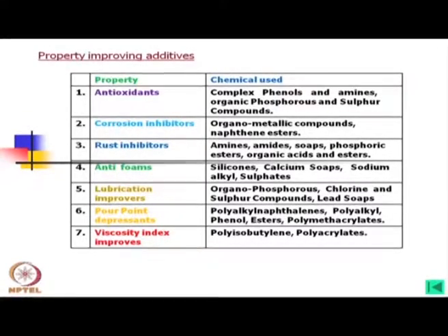Now, as such that foam may not be that harmful, but with that foam the air bubbles go inside the oil and that creates a problem. So, it is better there should not be much foam. This can be controlled from the outside also using, say, a baffle and separator inside the tank, but these chemical compounds will help in a better way.